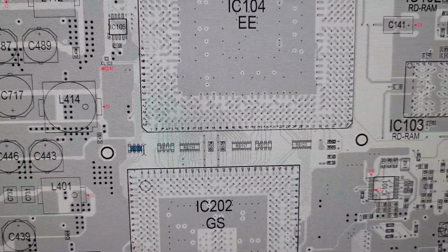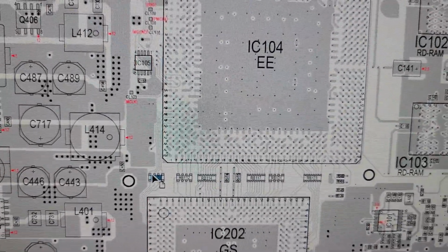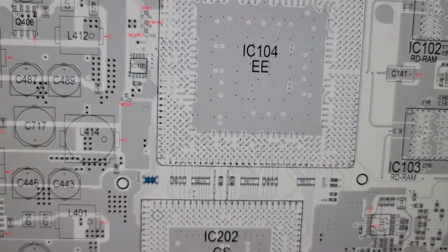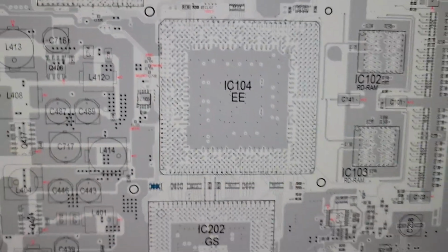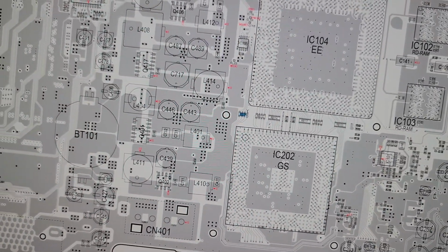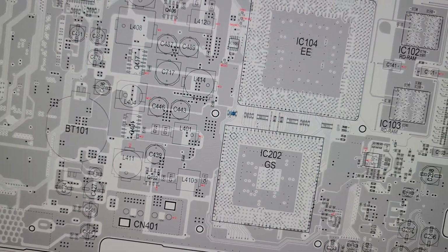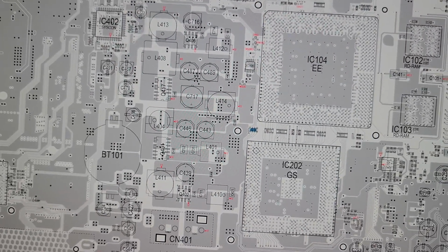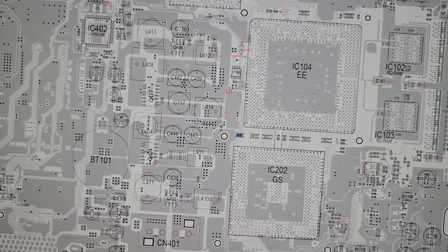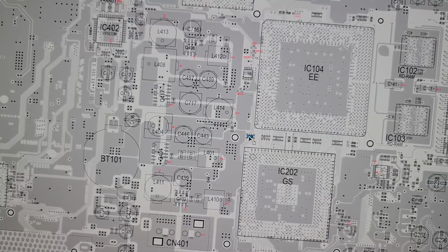They're resistor ICs. That's what they are. I'll show you in the parts diagram what they are. These are supposed to be 47 ohms each. Each little leg is 47 ohms. So if you got 47 here, 46, 46, 47, and 90 ohms over here, that's your problem with the no video and the board not booting. And nothing's communicating, because these are data bus lines. They're network lines. They're like data bus lines on a car, okay?